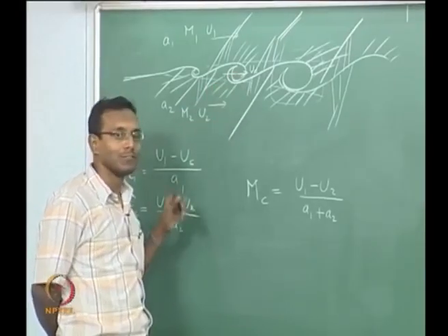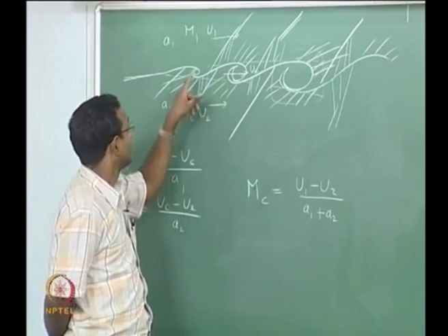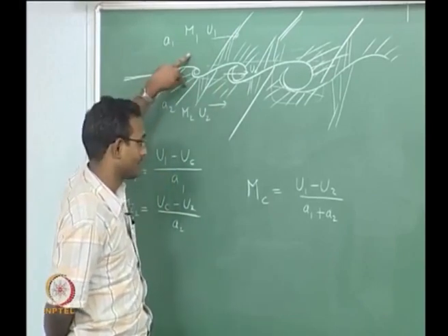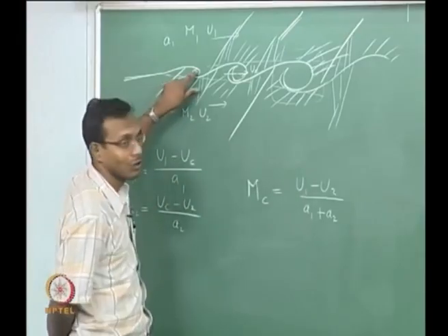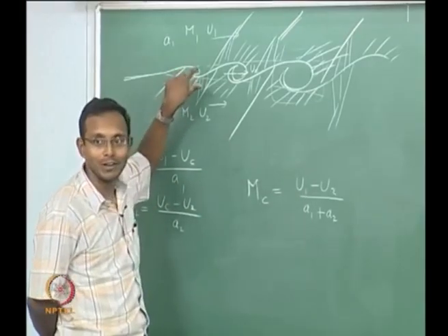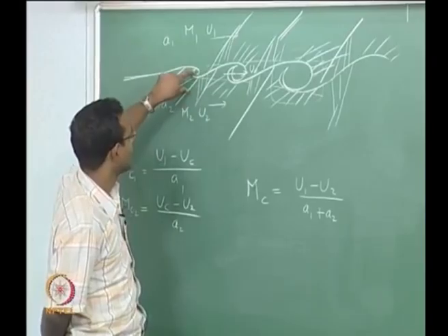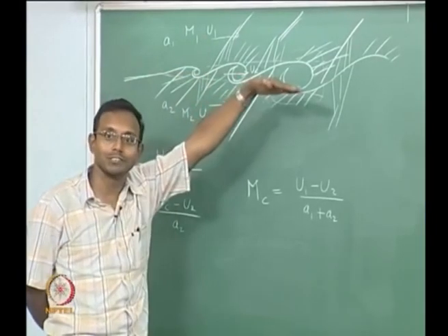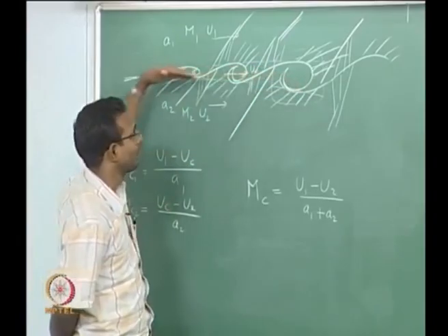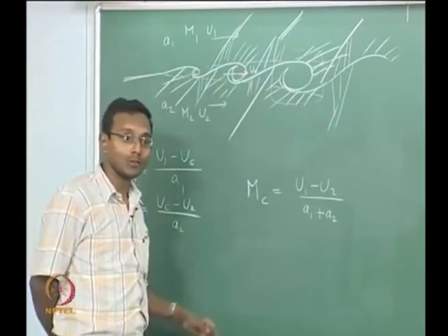If you want to think about it from a fluid mechanics point of view, the velocity difference is so high. When I say this number is high, u1 minus u2 is very high, which means my vorticity is very strong, and vortex breakdown occurs. It is no more just a 2D vortex, it breaks down and becomes streamwise vortices, and those streamwise vortices cause a lot more mixing.